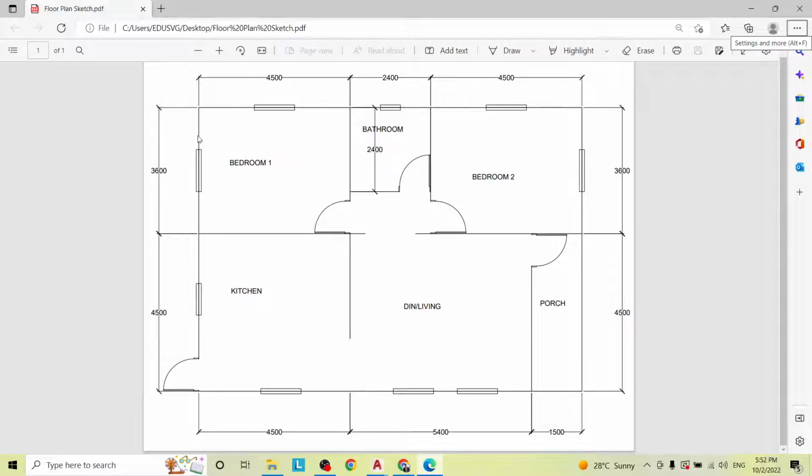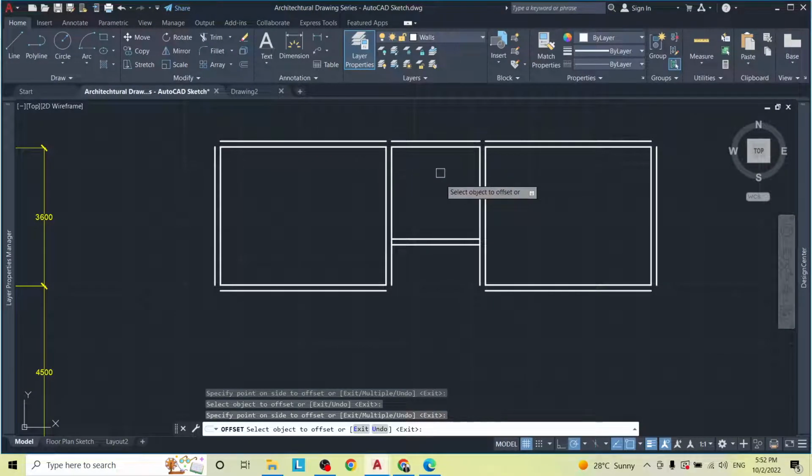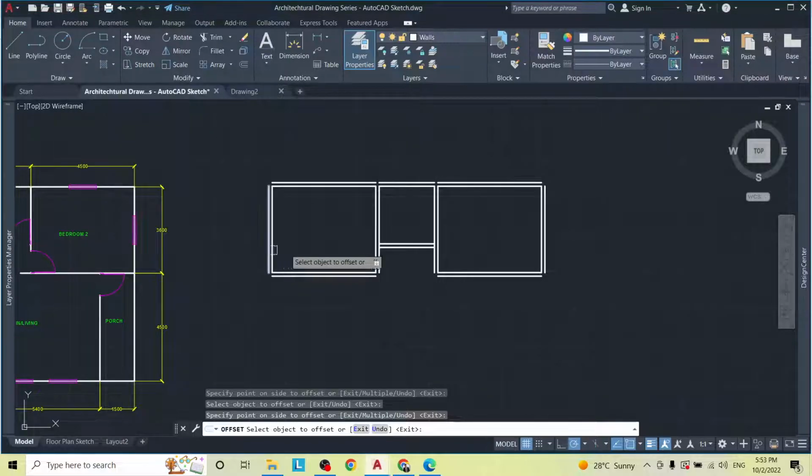But if you include the thickness of the wall, it's going to be 38 feet of inside measurements plus half foot here, half foot here, that's another foot, so that's 39, half foot here, and half foot here. That's another foot. So the entire thing is 40 feet, right? Okay, so let's just continue to build this out.